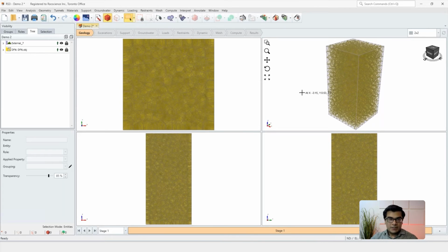So my point here is that when you are doing the divide all for a joint that is coming from the DFN, it is not splitting the original volume that you assigned the DFN to. It is smart enough to glue those small pieces back together and keep the original shape of the external boundary.